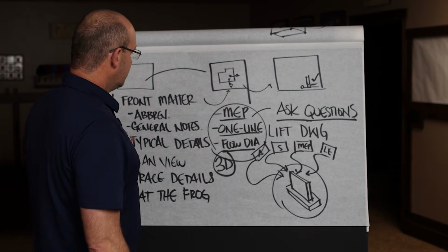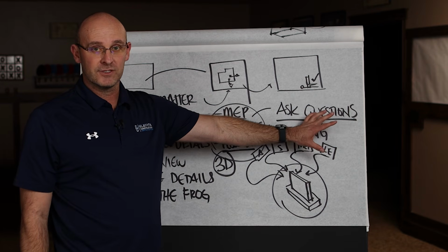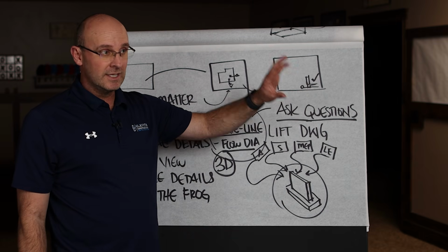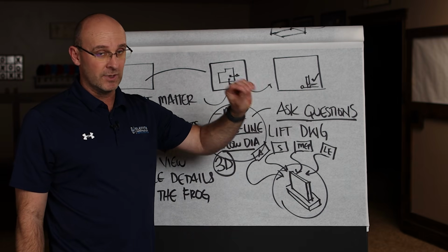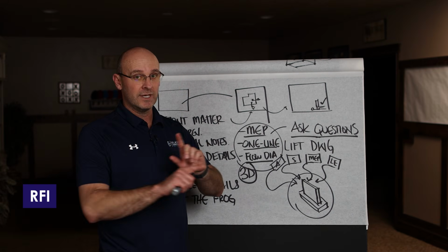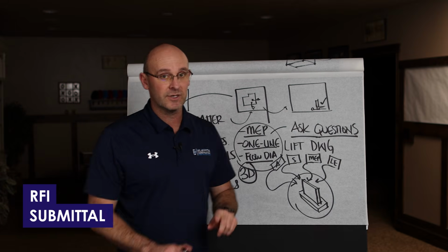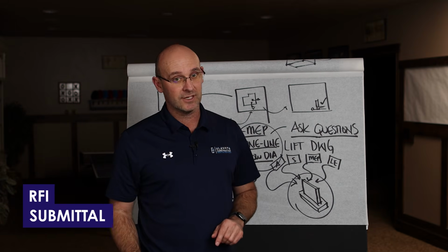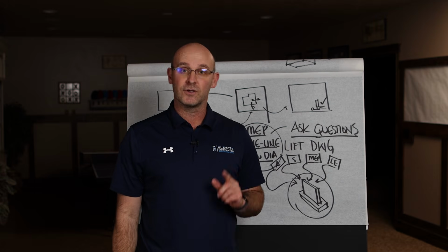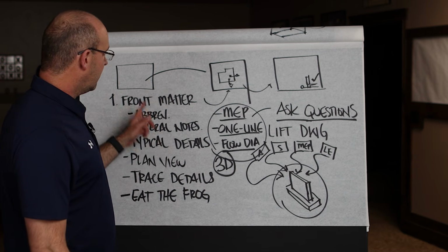One other thing, don't ever scale dimensions from the drawings, and don't ever assume. If it's not on the drawings, our legal precedent for this is you must write an RFI and receive a response and post it to the drawings. We never assume, we do not design through the submittal, and we do not guess, and we do not scale dimensions. If it ain't on here, don't go out and try and build it that way. You'll get yourself in trouble. The drawings are our base.